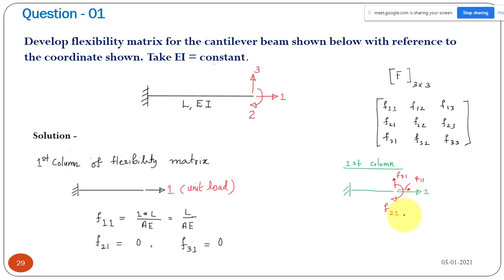Okay, if you have a bar element and I apply axial force P, the axial deformation is delta equal to PL by AE, where the length of your beam is L. And due to the axial force, what is the value of the deflection?